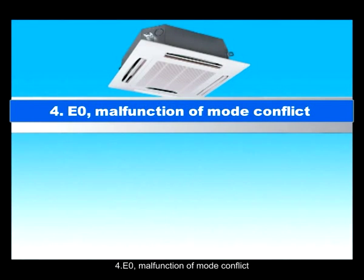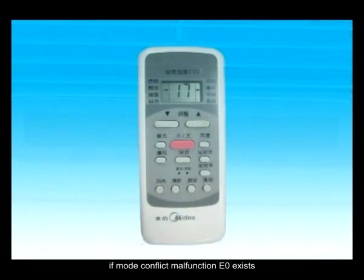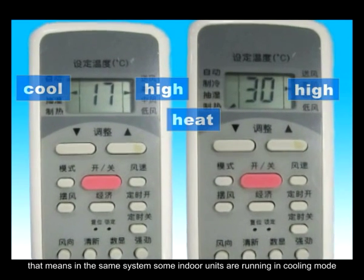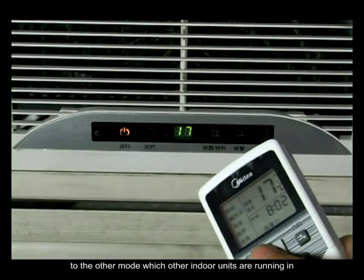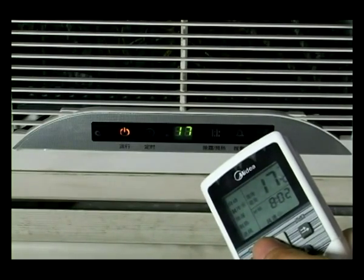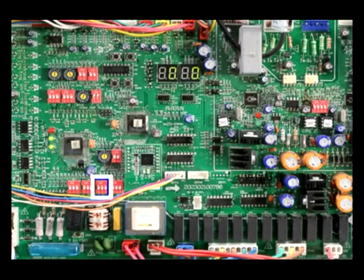4. E0 malfunction of mode conflict. Repair instructions when E0 appears. If mode conflict malfunction E0 exists, that means in the same system some indoor units are running in cooling mode and other indoor units are in heating mode at the same time. The malfunction can be solved if you change one running mode to the other mode, which other indoor units are running in. We can use outdoor mode lock function to lock the indoor unit running mode. That will help the customers operate more conveniently.